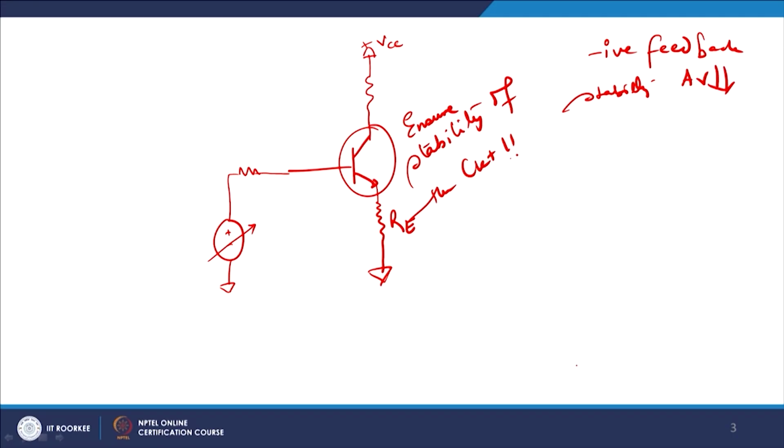So, if I do a negative feedback in the voltage domain, which means the output voltage is fed into the input voltage side with a 180-degree phase shifted value, then I can safely assume that my overall gain will reduce, because the principle of superposition can be applied and the two voltages will be added algebraically.